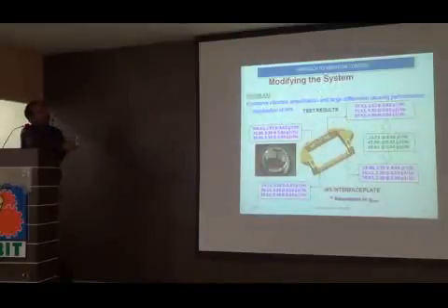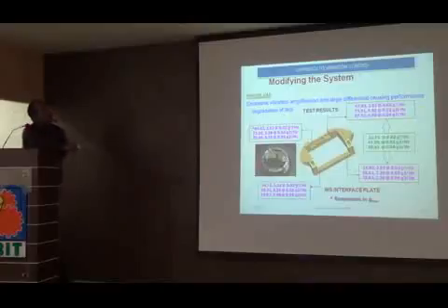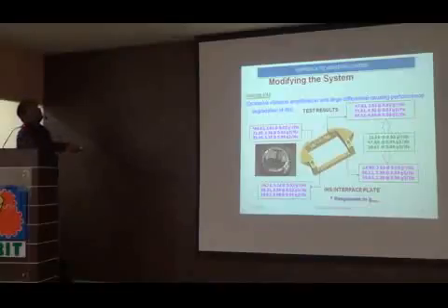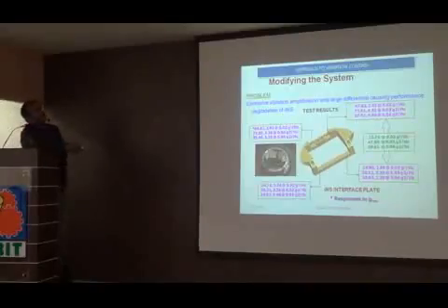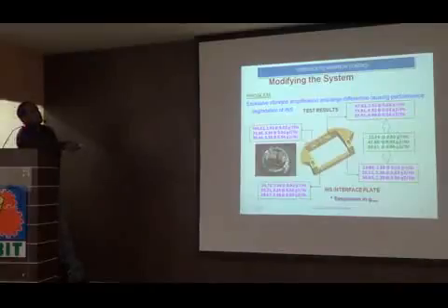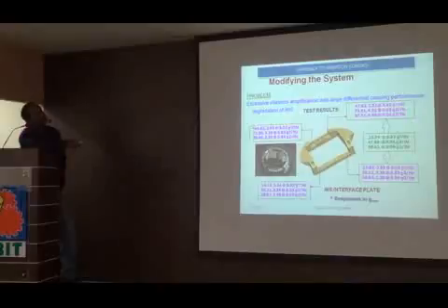Yes, we did one of the system modifications I just explained. We did quite a few. One of them I will explain. In one of the Agni series of systems, the INS, what we call the inertial navigation system, is mounted with the help of a bracket onto the section where all the electronic components are mounted. This system was experiencing very high levels for the given input. The system was failing. So the problem was excessive vibration amplification and large differential input causing performance degradation of the INS.